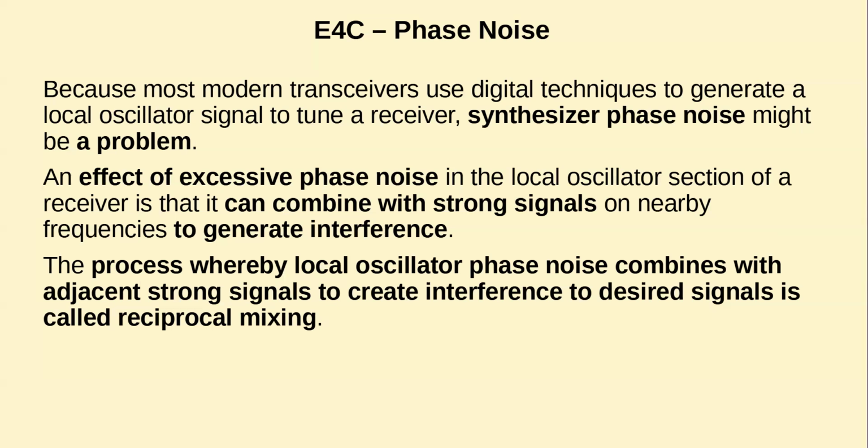Okay, phase noise. Phase noise is just, I call it phase jitter, where there are slight variations in the phase, or some very small phase shifts of the signal. That's called phase noise. It's kind of inherent in the oscillators themselves. When noise gets in there, it can affect the tuning circuit enough to actually just change the phase, not necessarily the frequency.